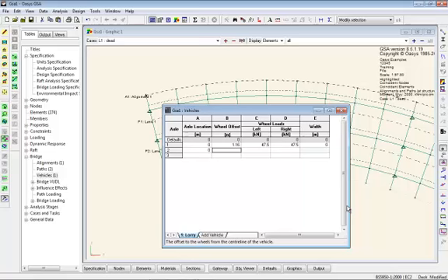Another backwards, double wheels at the back, 0.84, 47.5, 47.5, and then the front wheels, which are 4.5 meters further ahead, 1 meter offset. There's a 2 meter wide vehicle with just 45 kilonewtons on these front wheels.